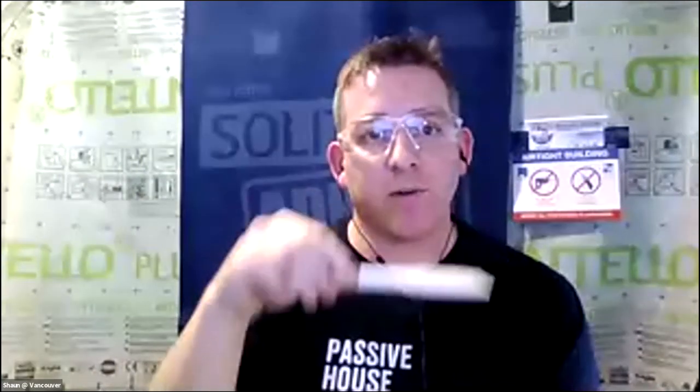Because a lot of times you're looking at air leaks. When we put our tape on with our hands, you can get a little bit of tenting in the corners where you've got a little bit of a rounded edge. And when you have a nice tool, you can get a nice 90-degree corner pressing the tape into place.